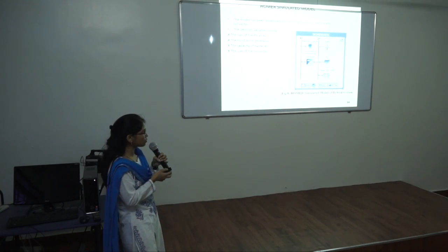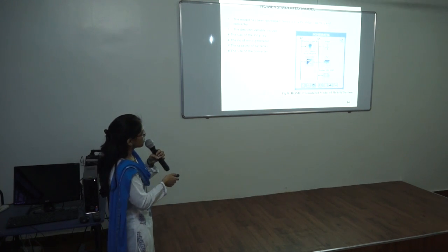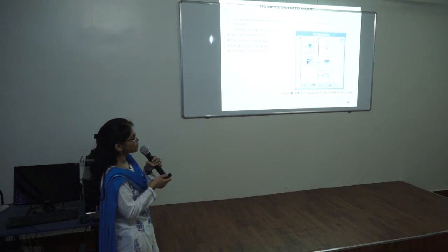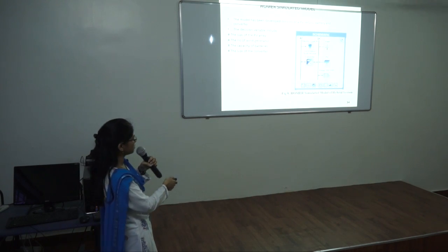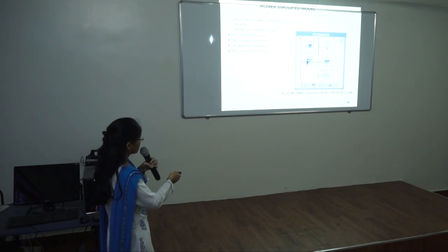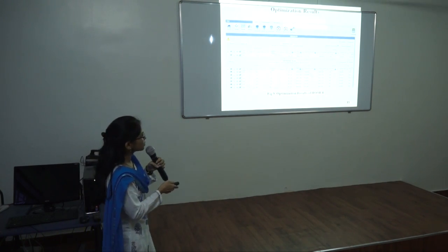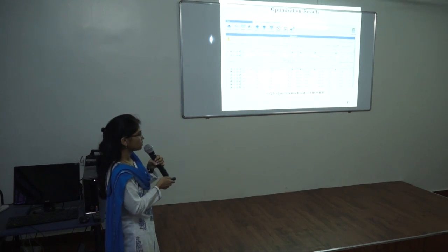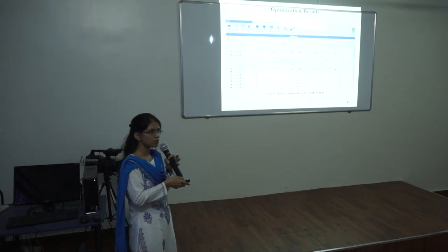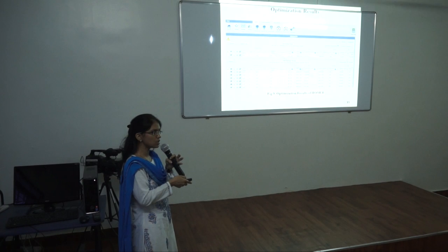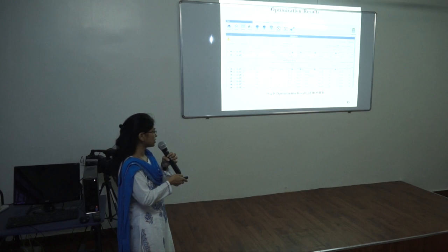The excess energy generated from PV and wind is stored in the battery until it reaches its full capacity. The main intention of introducing the battery storage is to import or export the energy as per the need. By considering all this, HOMER repeats simulations to get the feasible solution. The criteria for selecting the best component of the hybrid energy system is based on minimization of net present cost, sustainability, maturity of technology, efficiency, and generating minimum excess energy.